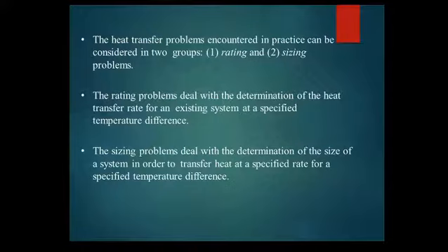Then sizing problems deal with determination of size of the system in order to transfer heat at a specific rate for a specified temperature difference. So in this sizing problem, designing of the tube, diameter of the tube, length of the tube, how many bends you need, how many number of tubes you need, how many number of fins you need, all those things are calculated.